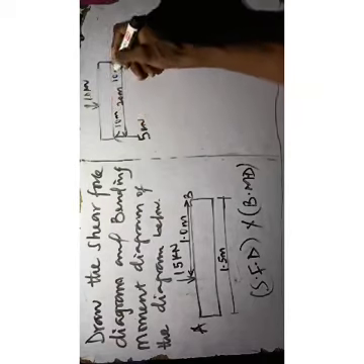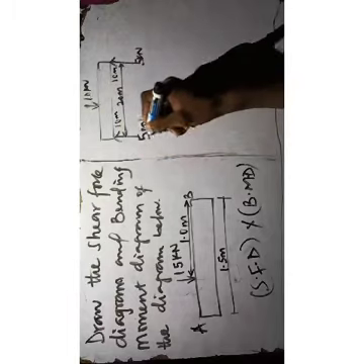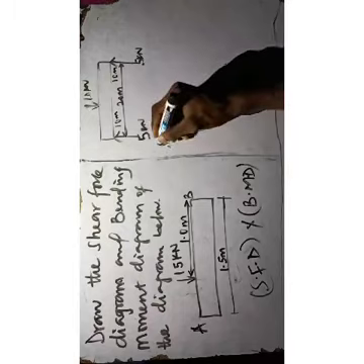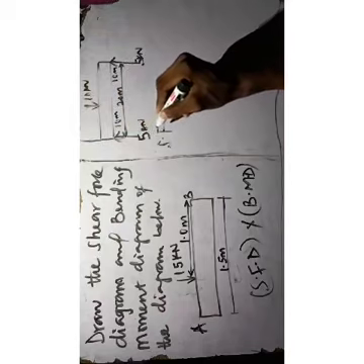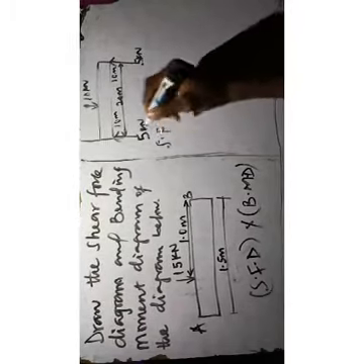Okay, so you must take the bending moment at each point and the shear force at each point. Here lies the stress. Okay, and it's very simple. So what you do is you find out that at point A, if you are to take the shear force here, the shear force is just, you consider the force. That means if I cut this point away, if I'm cutting this point as initial, my shear force will be equivalent to the force acting on it.